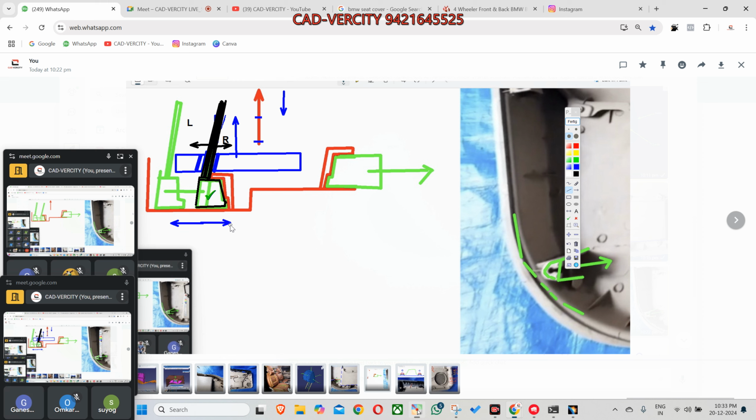Good, Ganesh. Okay, but now this is the close condition. The lifter is in good condition, it is under the doghouse. Now suppose injection is completed and solidification is done. Now I want to open this core and cavity. I will push this mold upside. What will be the result? Now, tell me where the lifter will move. I'm opening the mold. Where will the lifter move?